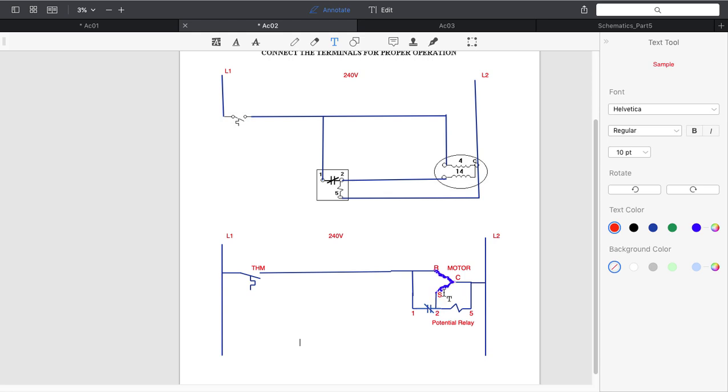The start winding, though, because it's a coil of wire and there's a spinning magnet in that motor, continues to power itself and provide power to that relay coil until the motor stops. When the motor stops, this contact will go back into its normal position, ready for the next run time. Potential relay, pins 1, 2, and 5.